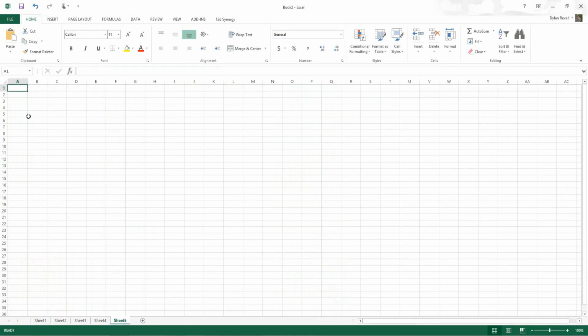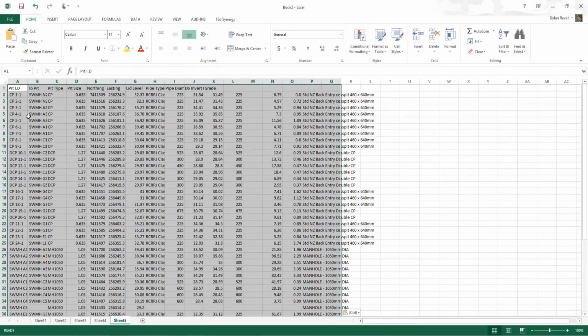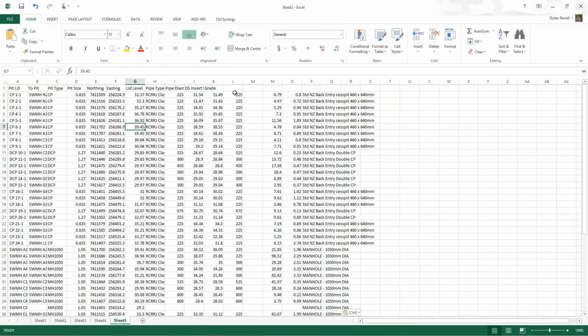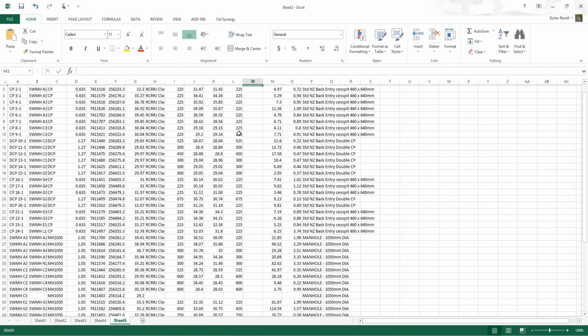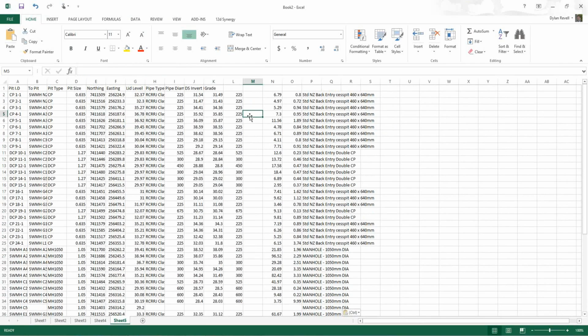In this case, I'm going to paste that into a blank worksheet. So you can now see that I have a blank column which will be available for doing calculations inside a pre-formatted report file that your company may have. Just if you are going to be doing that, whenever you paste directly from the spreadsheet clipboard, if you have a predefined formula in a particular column and you do the paste directly out of 12D, it will overwrite whatever formula are there.